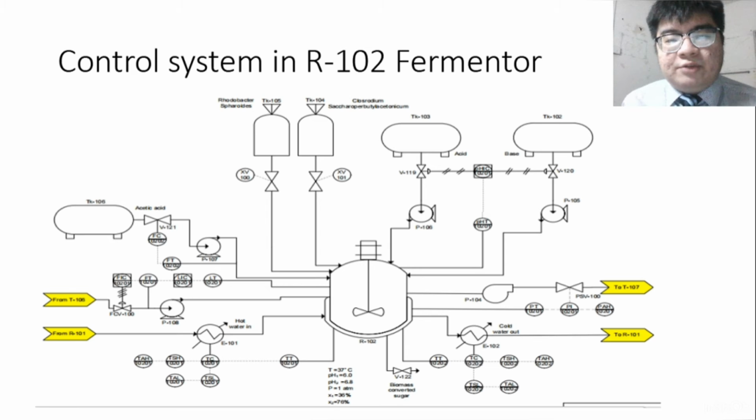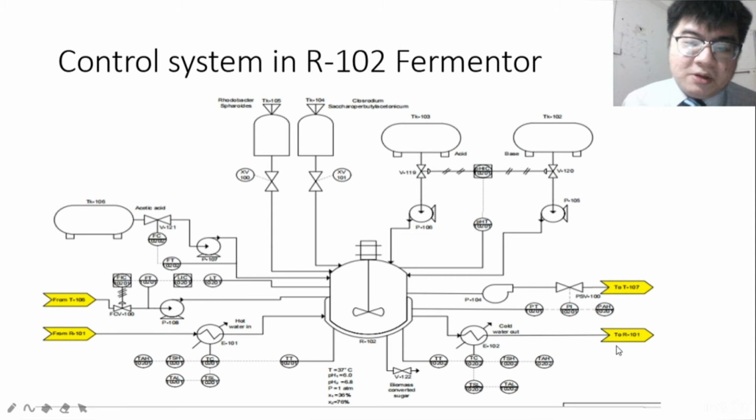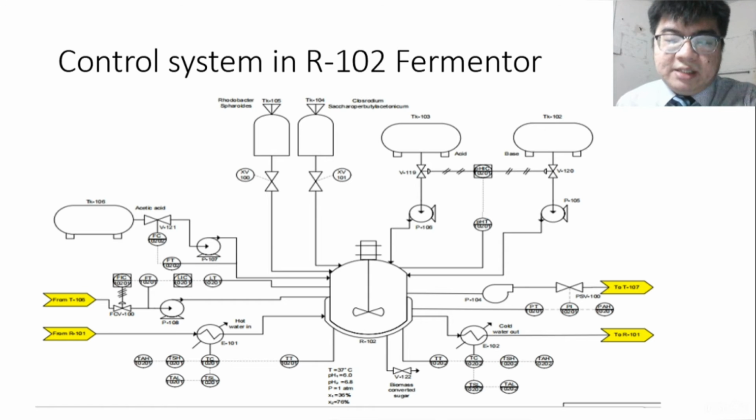Once the pressure reaches the set point, the regulator closes and no longer allows the air to flow. So for safety strategy, an emergency alarm is also installed. When the pressure is high, the alarm will be triggered and alert the operator.